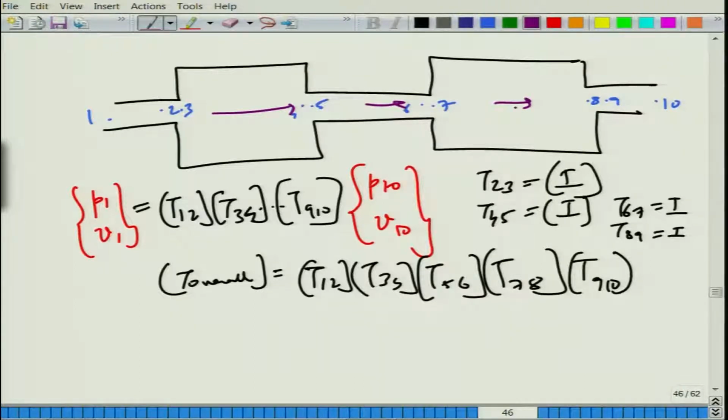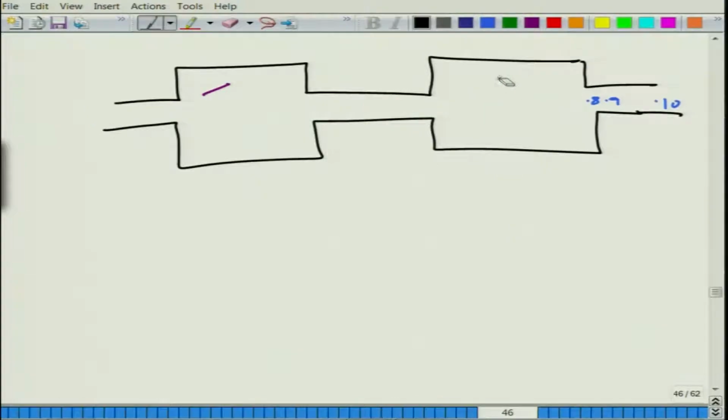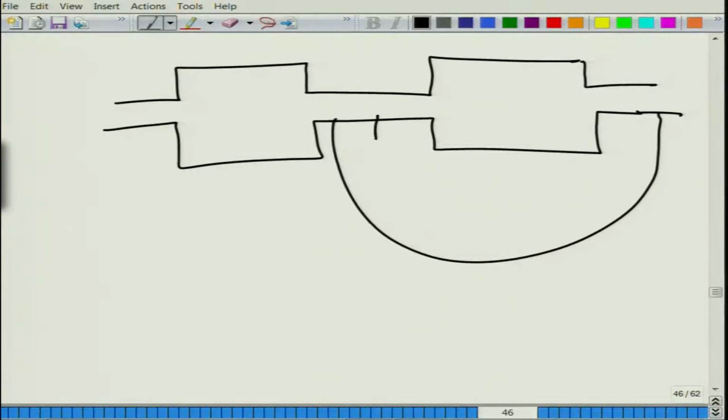For a typical commercial muffler, you typically have two muffler shells attached to each other, one upstream and the other downstream, and internally you can have a very complicated structure here and very complicated structure here. But still the wave propagation path is unique from upstream to downstream. But now let me just rub all these things out and introduce another path to the wave propagation. So, let us say what I am going to do is also get rid of these numbers and introduce this thing, something like this.